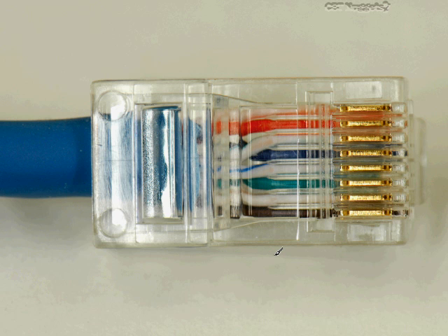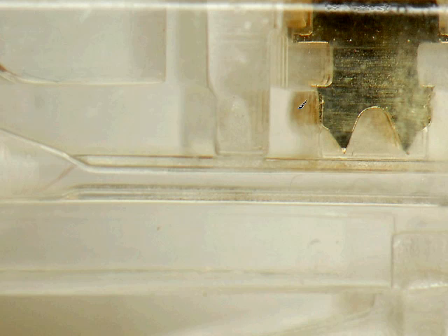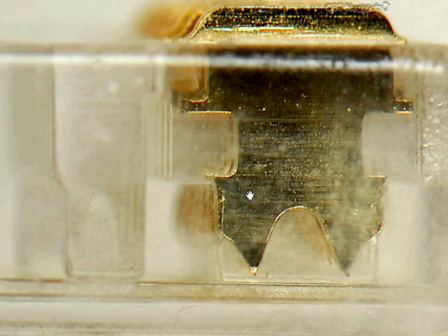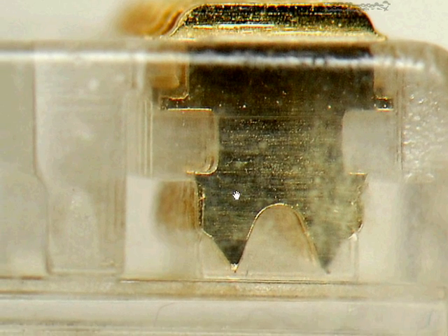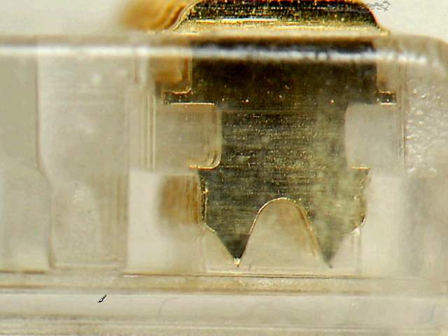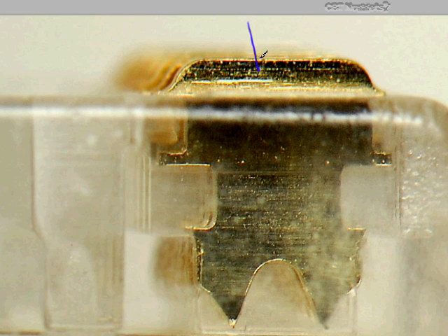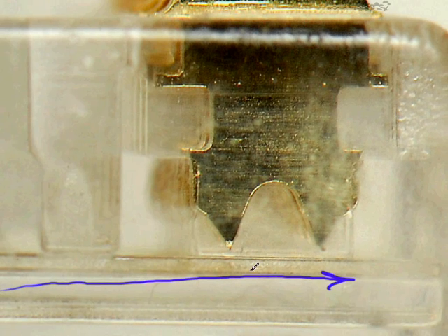And then when you actually plug this into a hub, a switch, or a network interface card, these contacts right here that you can see are what actually make contact inside of those types of devices. Now, when you actually wire this, this is a side profile view, a macro view, so it's highly magnified, of the actual piercings that take place. The individual wires that we looked at a moment ago will go into this portion right here. They'll just be fed right through here. And then you'll take a crimper, which clamps down on top of these plungers, and they will then press down using these pointed tips down here. They'll pierce into the actual wire down in this section.